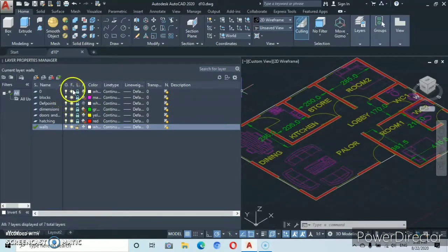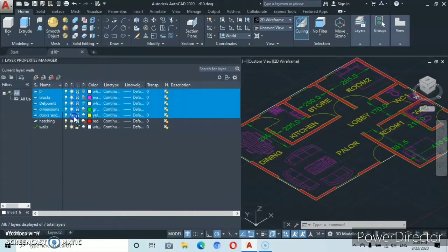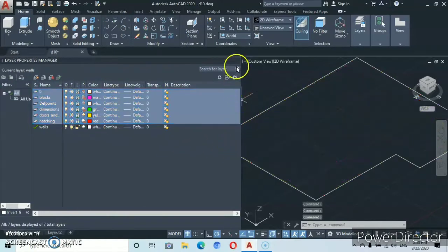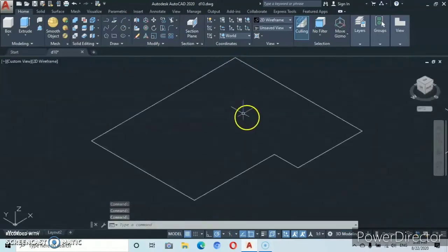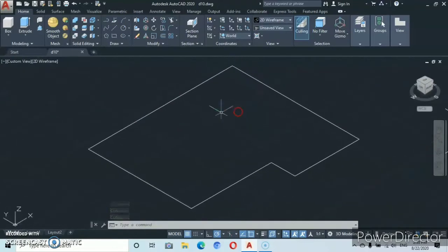Then now let's select, okay, we select the layers that we previously locked. Then you're going to see freeze. Okay, you click on freeze, then you come to close. Now you're going to see that we've frozen the features that were here because we already had our traced line.